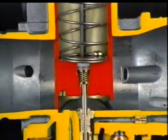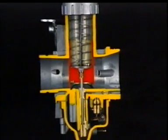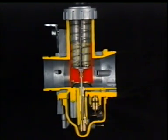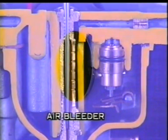The carburetor also involves a number of other elements, and all of these various processes make it possible to supply the ideal fuel-air mixture to the engine to match the current driving conditions. For example, air bleeders are provided in both the main system and the pilot system at the point where the fuel and air intersect. These air bleeders help to turn the fuel-air mixture into a spray.